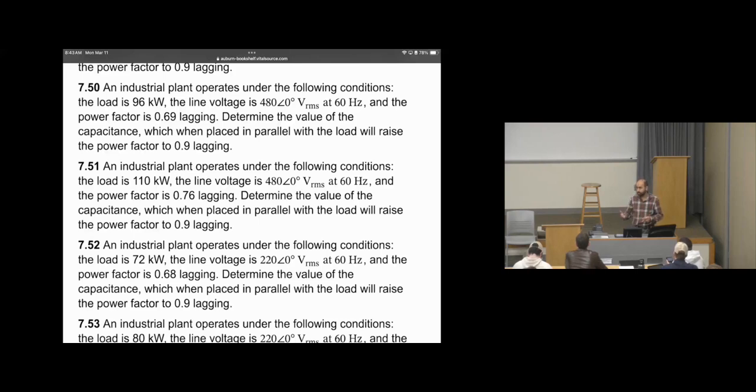So you will go to the market. You will see several types of capacitors. You can find something large, something small, depending on the cost. So the next thing, now that we agree we need to install a shunt capacitor or power capacitor bank, whatever we call it, your target as an engineer is not only to say, let's use this. What's the best value that we need to use so we can improve the power factor to 90% and avoid the penalty?